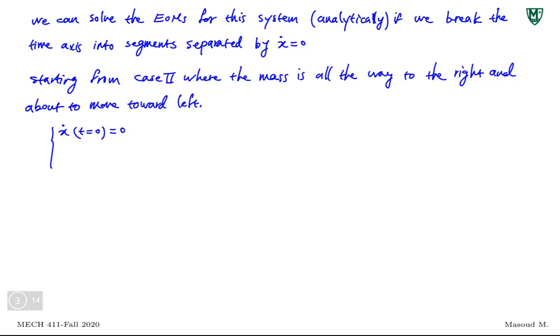So the velocity is 0, meter per second, millimeter per second, whatever the unit is. Now, when we're all the way to the right, we are at some distance, x naught, whatever the distance is. I'm going to consider that as the initial position for the system. Now, I have this along with the equation of motion, which we already found when we're going in that direction. We said it's m x double dot plus k x is equal to mu n. That was the equation of motion.